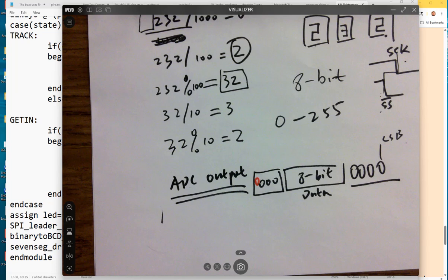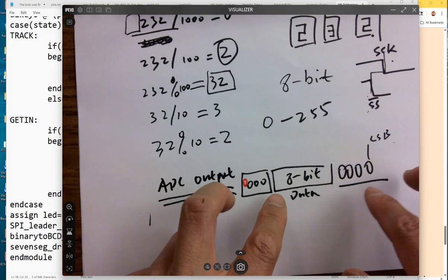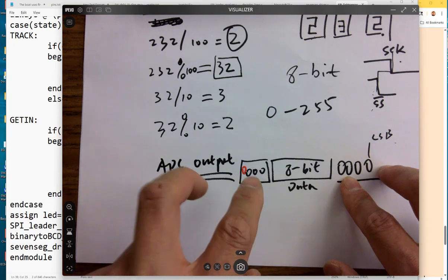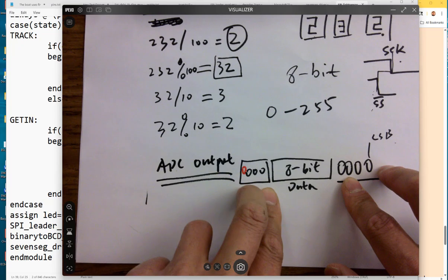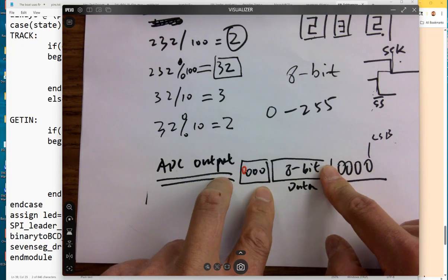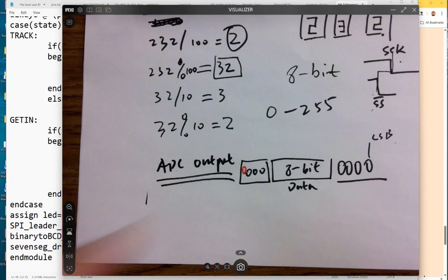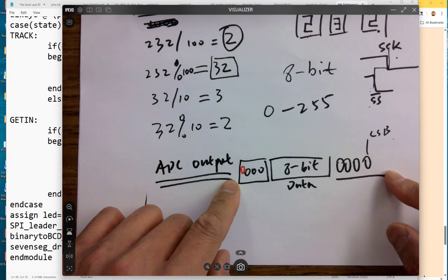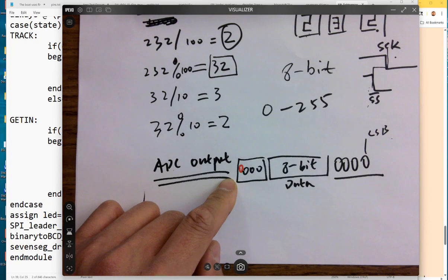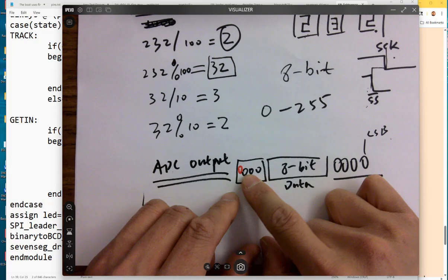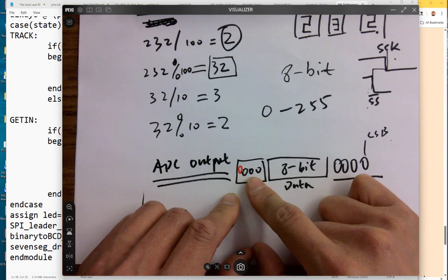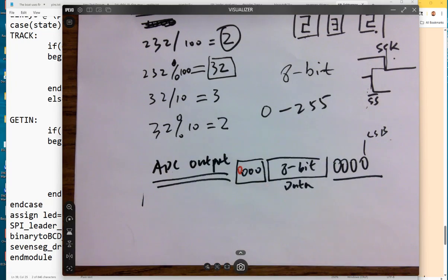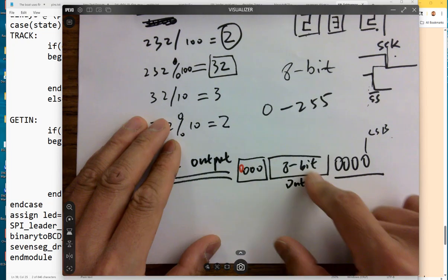And I don't know why, but you're going to expect 4 trailing zeros and 4 leading zeros, sometimes 3 leading zeros. In the middle, you have 8 bits of data. So just in case it becomes 16 bits, right? I just use my SPI to receive 16 bits. And I don't need all these bits. I don't even care if there's a 0 here. I'm not using it. But I do have this capability to receive 16 bits, and then only take out these 8 bits as the data.